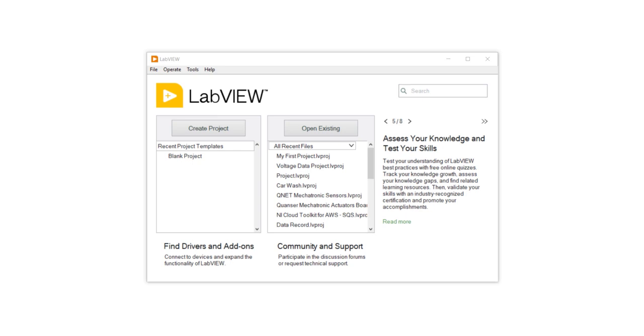So in data acquisition there are two parts. There is one sensor which will sense the physical changes, and using the data acquisition module we can acquire the data. After the acquisition we can analyze it and take our desired output. After that, we can generate some information to rotate any motors or control any physical objects, and that is data generation. All these things you can do using one DAQ.